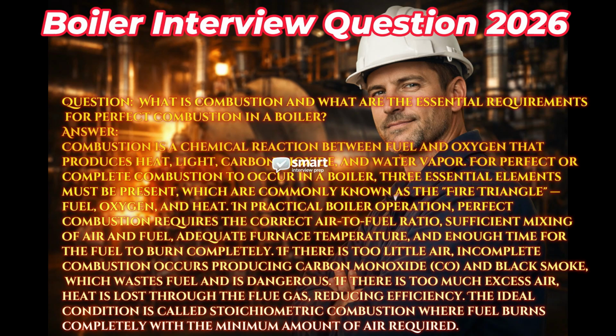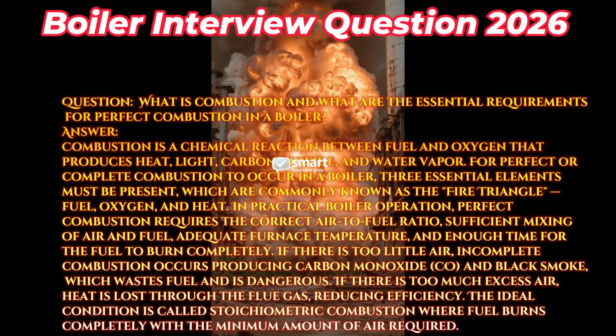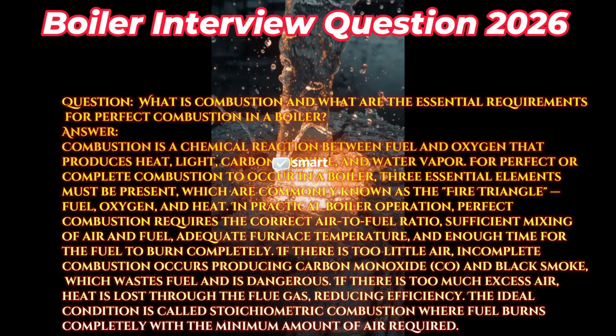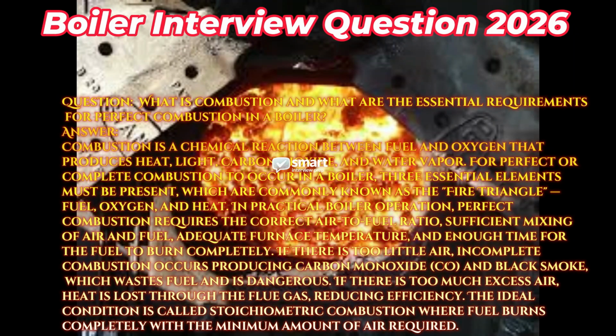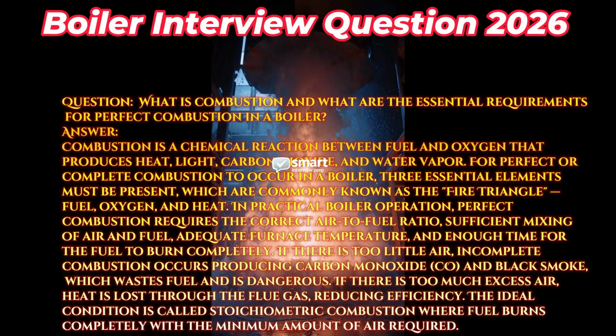Answer: combustion is a chemical reaction between fuel and oxygen that produces heat, light, carbon dioxide, and water vapor. For perfect or complete combustion to occur in a boiler, 3 essential elements must be present, which are commonly known as the fire triangle: fuel, oxygen, and heat. In practical boiler operation, perfect combustion requires the correct air-to-fuel ratio, sufficient mixing of air and fuel, adequate furnace temperature, and enough time for the fuel to burn completely.